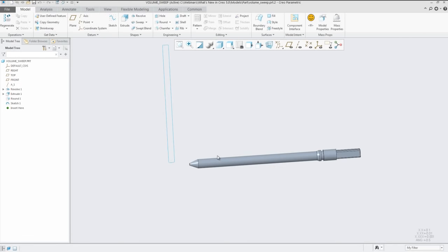Okay, so with the introduction of this new tool, we can accurately model geometry resulting from cutting tools used in manufacturing operations. Supported use cases cover grinding wheels, screw conveyor scenarios, etc., where in both cases the sweep is performed along a helical curve. Material is removed where it intersects the part along its trajectory, and then from the helical sweep dashboard, you can easily define and control the parameters of the helical trajectory.